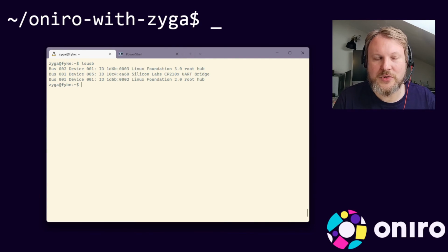And that's it. Now I can use all kinds of interesting tools. We can use programming tools like flashers, or we can use serial adapters. You're going to have a lot of basic things just work. There's a small caveat. If you would like to connect something like storage, like a removable USB drive, that's not going to work because the kernel that WSL is using by default just doesn't have drivers for that. But fortunately, we are not limited by this case here.